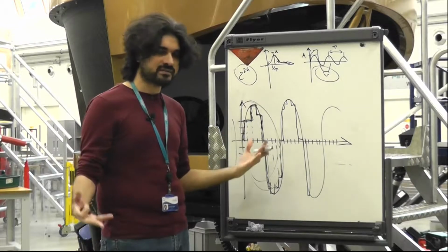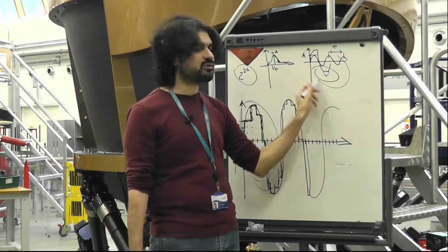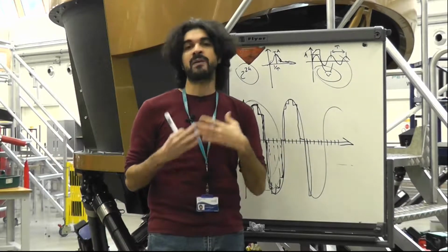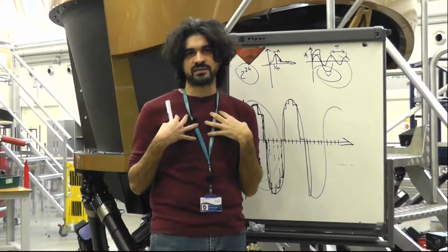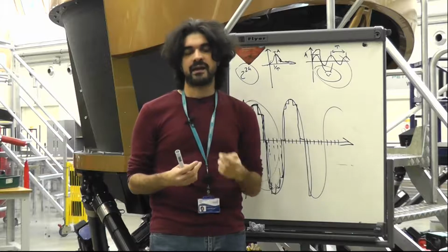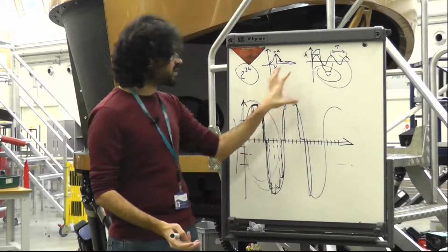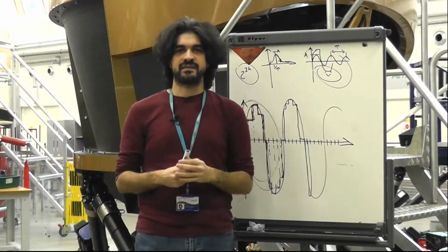So you want to avoid being too low in your range, and you want to avoid being too high on your range, so you have to set a level of amplification of the box for every channel. Every channel has its own amplification, and you want to set it so it's about 80%, 90% of the full range. That's the ideal range.